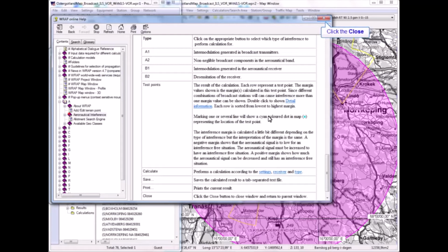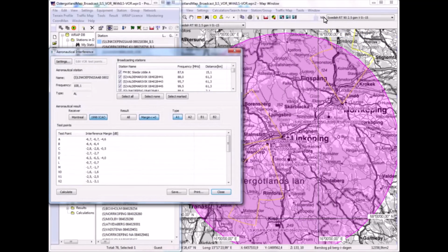So we have A1 cases, multiple A1 cases, and that is generated in the installation. Of course, it's not at all certain that this intermodulation really is generated, but the method identifies that there is a risk using the default characteristics defined in the recommendation.